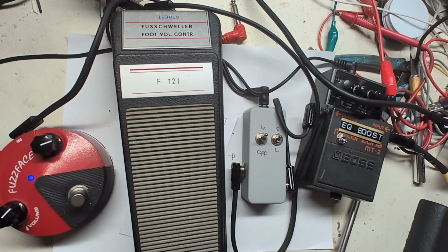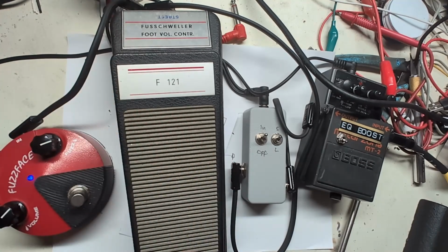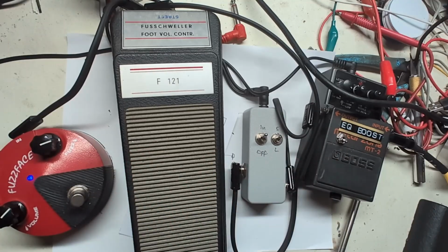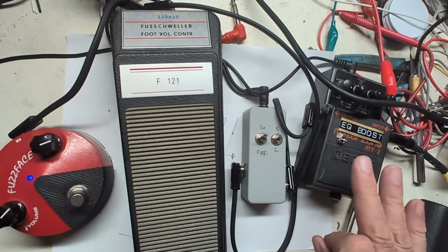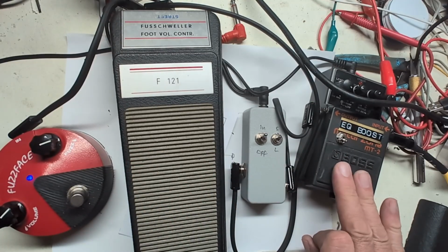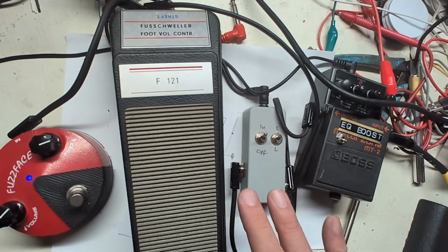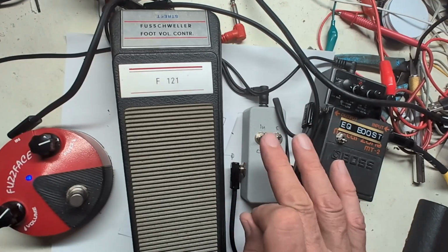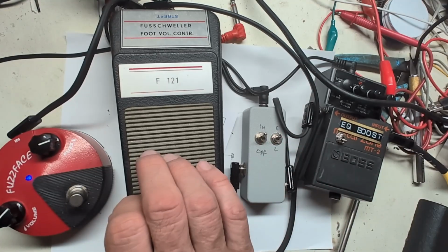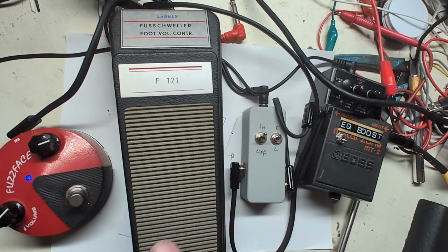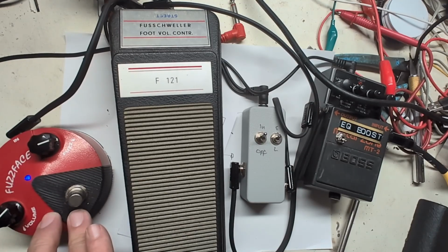which is fantastic because now we've isolated this circuit here from the rest of the pedals. Like the boss pedal with all its buffers and everything is now isolated by a buffer in here, and then the inductive element, the inductive capacitive resistive element that we added. Then we can use this to give us full expression now with our feet as opposed to using our hands and the volume pot, and that allows us to get the most out of our fuzz face tonally.